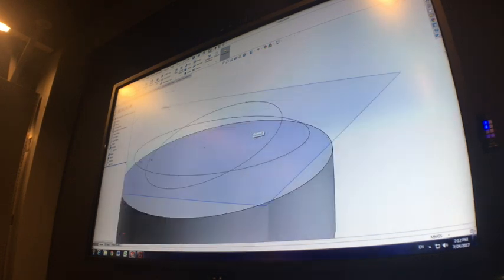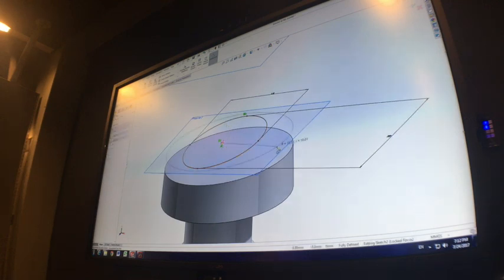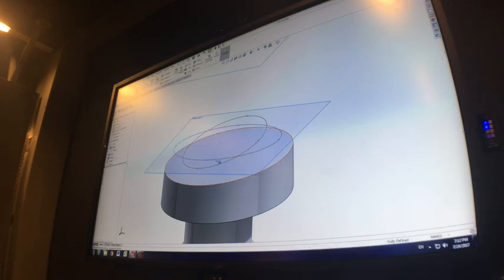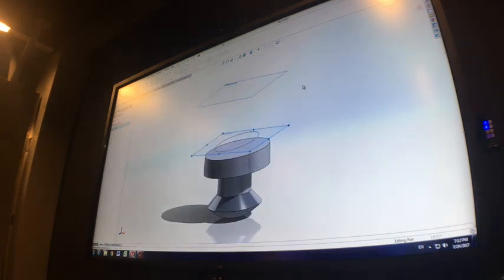So if you accidentally sketched two ellipses in the one sketch file, you just have to delete one of them. If you've sketched both ellipses on the same plane, that you can just fix. So you can click on the sketch that you want to move, and there's a little shortcut that pops up that says Edit Sketch Plane. That enables you to change the plane that sketch is on. So you can change it from being on plane 1 to being on plane 2, and it will move that sketch up to that plane.